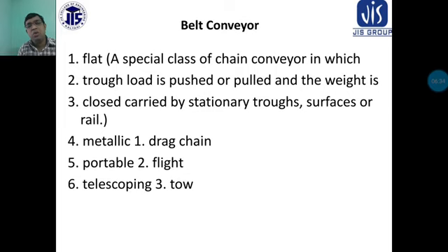And during this movement, suppose you keep the product staying in the solidification procedure, then your second product will not be produced at that time. For this you require movement of your product from the casting place to a far distance, and you also require space for the second product to come out from the furnace. Then for this you have to use belt conveyors, where the products move, the belt also moves, and the output products also move, and the solidification procedure is done during the movement from one place to another place.